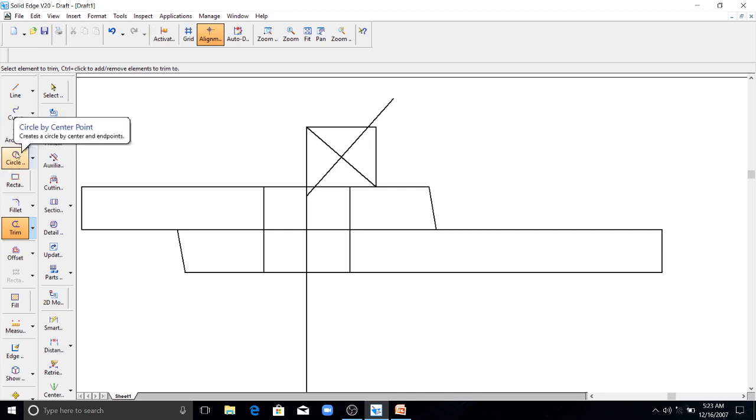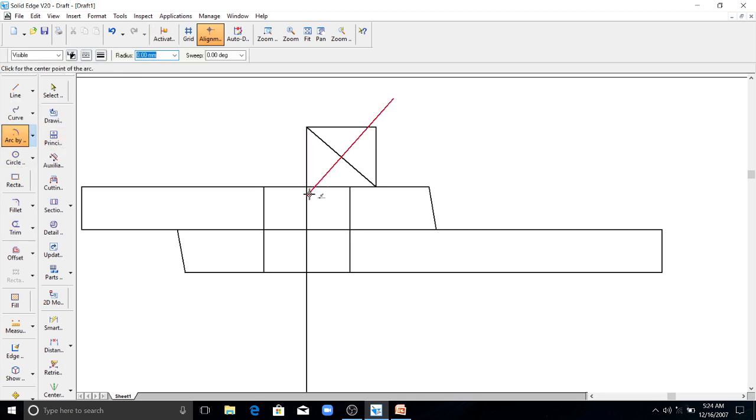With this center, now you have to draw the arc. This is your center, and radius equals 0.8 d, that is 14.4 mm. Your 14.4 radius is here. This one I have already drawn. So you have to draw an arc now. So this is the procedure for drawing a snap head of the rivet. This is the radius of the snap head. These are construction lines. Remove them.